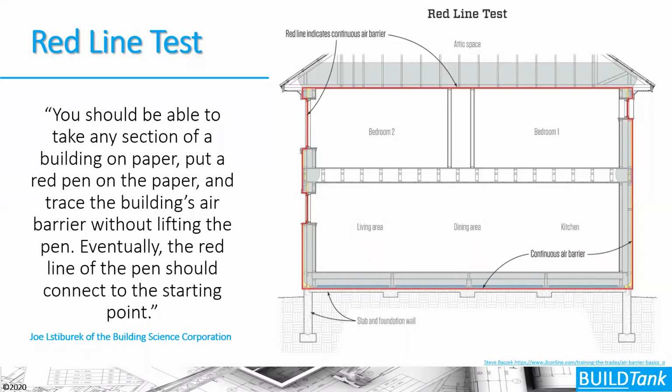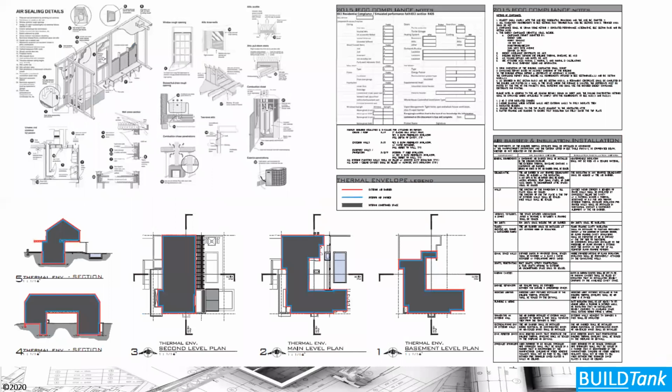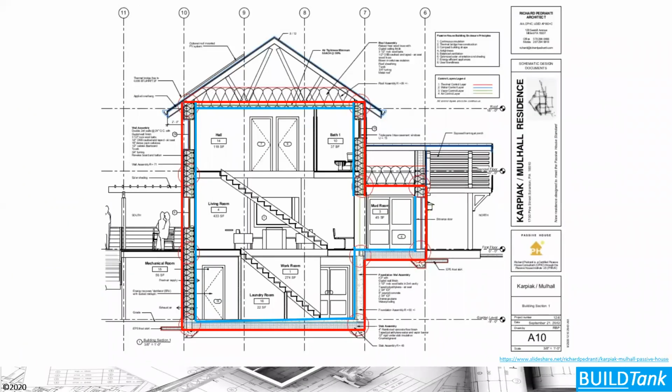What we see is that that's done in a lot of different ways in our construction documents now. We're seeing full energy pages being added to our construction documents that have depictions of our thermal envelope, that have air sealing details and insulation details and other details on it. So here's an example of a depiction of the thermal envelope on a construction document.